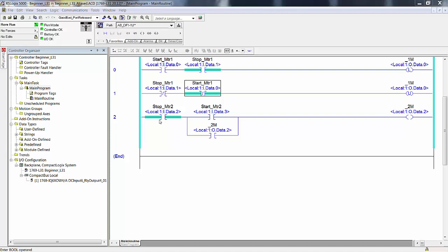Now because we're using toggle switches, we can toggle those switches on, the ones we're using for the stop inputs, and just consider that a normally closed button, because right now it's closed. It's at rest in the closed position. Keep it in mind that it's a toggle switch, so it has two at rest positions, open and closed.